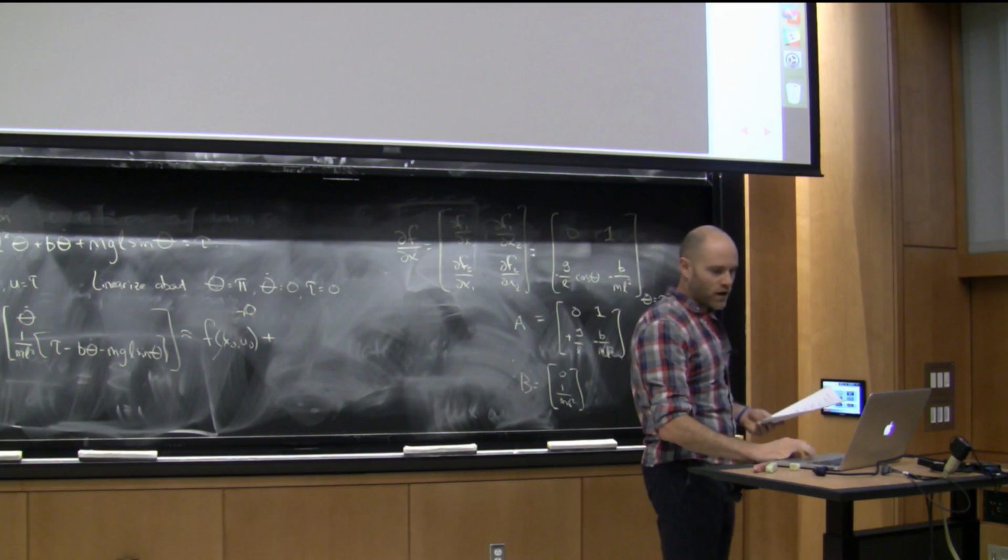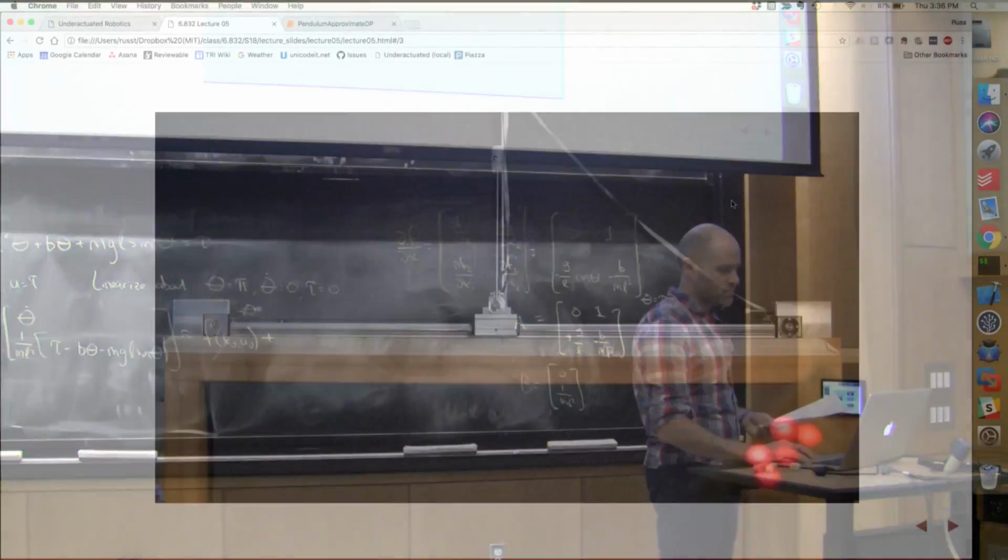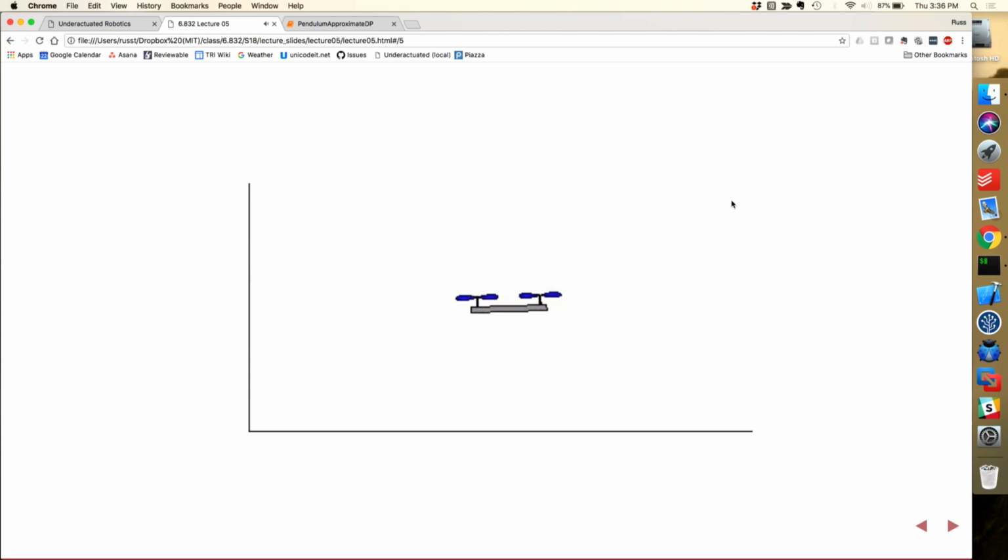And it's going to work for basically all kinds of systems. There's a planar quadrotor that's there. There's a 3D quadrotor, which the only problem is we're trying to figure out the best way to give you a 3D visualizer through Docker, right? Because Docker can't touch your GPU nicely. But this is the simple rendering of a planar quadrotor, and it's almost exactly like this, and you just pick the fixed point and you call LQR and it'll stabilize from a huge range of initial conditions.